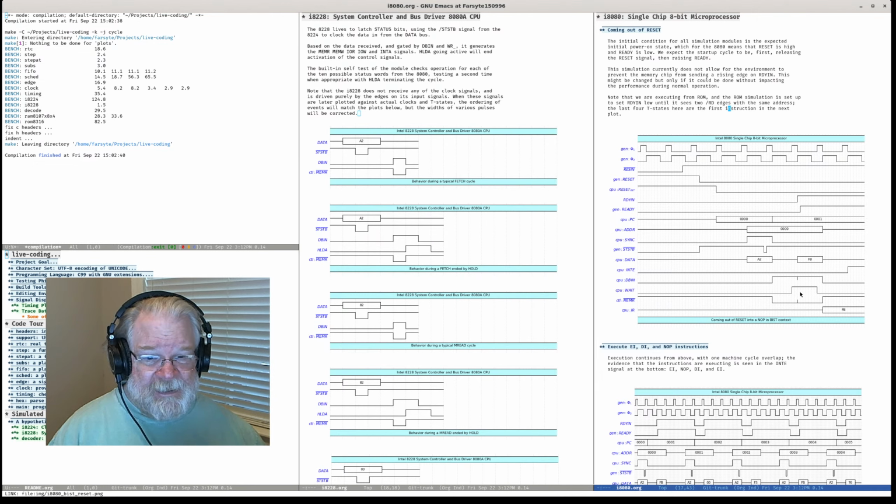We're going to see little teeny edges on here because of the way I am implementing this to get control back to the ROM to let it say we don't need another wait: we're sending another edge. I've covered this when I talked about the ROMs. So during this second cycle, when our ready is going high, we send out a ready in that is high, and we send out, here's the data. So our first instruction's an FB.